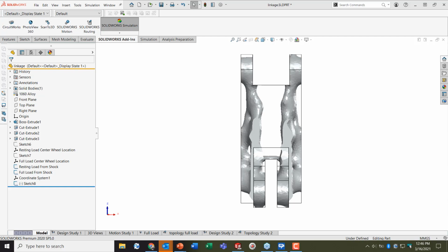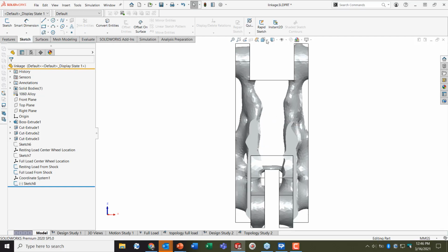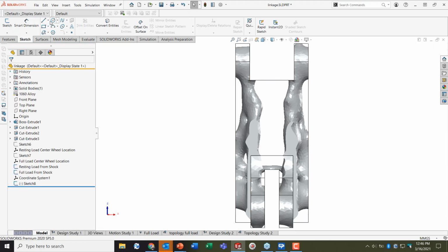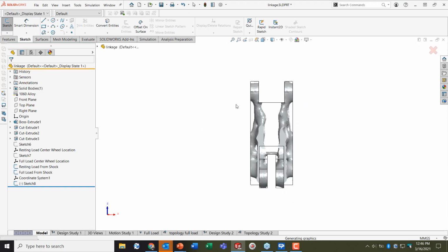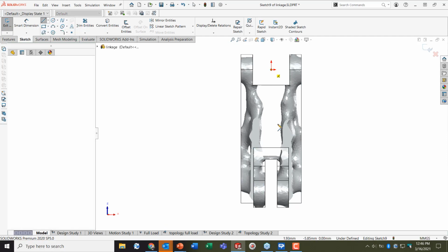With pulling the geometry in the sketch, is there a way to make it symmetrical to accommodate both sides? Yes. So, for example, this is just regular sketch modeling at this point. Remember, the simulation overlay is honestly nothing more than a very pretty graphic that is still very useful. So, for example, I'll go ahead and create a quick center line right here. Whoops, accidentally kicked myself out of the sketch. My bad. Let me go ahead and make a quick center line here.